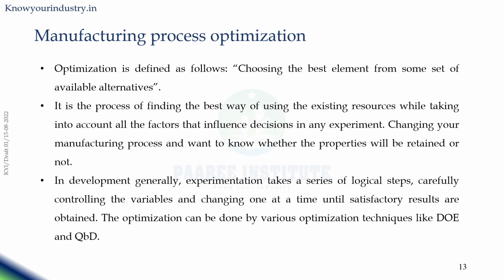This needs a design of experiments process where you can provide your design space. What is your operating range for each process? If you are making a solution, you should know the stirring time, the RPM, the sequence of additions, and the excipient range to be used to get your desired product quality. Every product's manufacturing process has to be optimized. If no optimization has been done, then you will end up with a lot of challenges when you transfer a product.